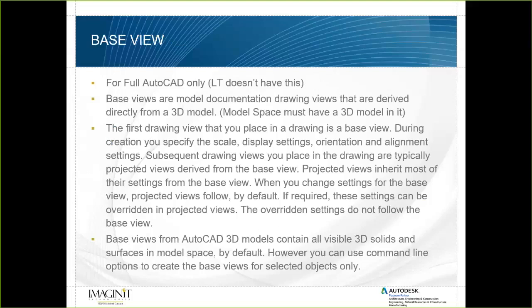So base view, just want to make sure that everyone knows this is for the full AutoCAD only. LT does not have this functionality. So what the base view does is it's model documentation drawing views that are derived directly from a 3D model. And I cannot stress enough that model space must have a 3D model in it. If it is just a flat 2D, it's going to prompt you to find an Inventor file, and I'll show you that.